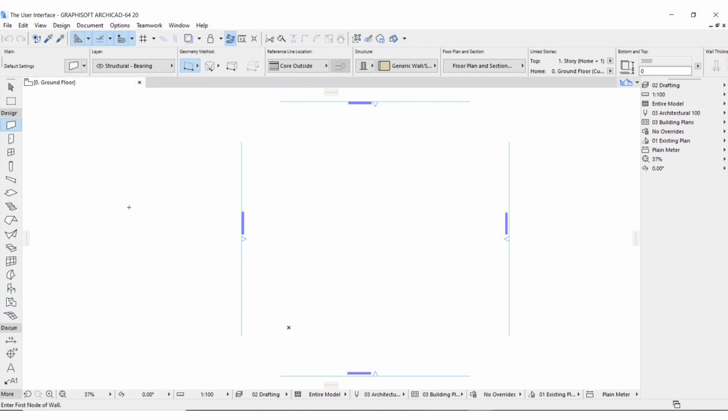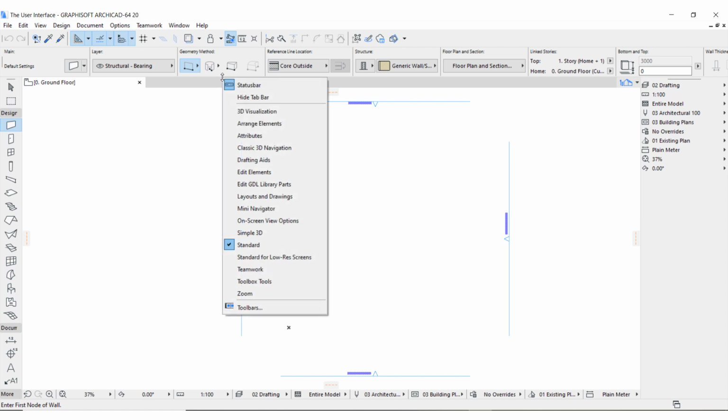Menus. When starting ArchiCAD with default settings, you will load the standard profile, which defines the default menu structure. However, there are some commands and menus in ArchiCAD which are not displayed as part of this standard profile. Use the settings in the Options, Work Environment, Menus dialog box to customize the content of your menus.